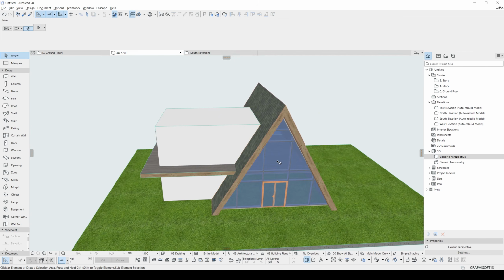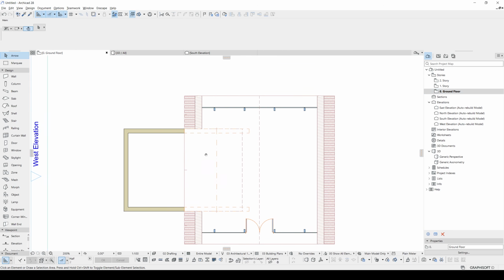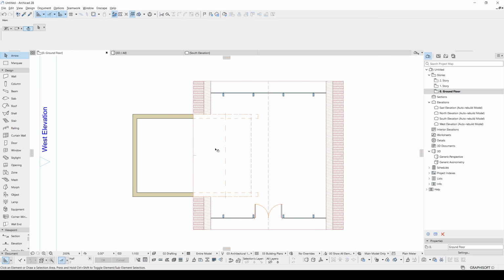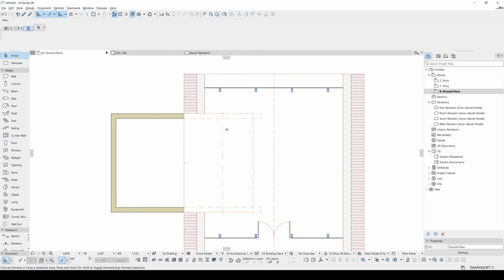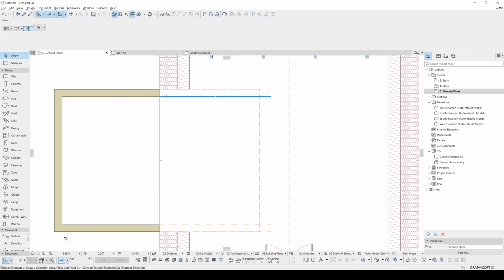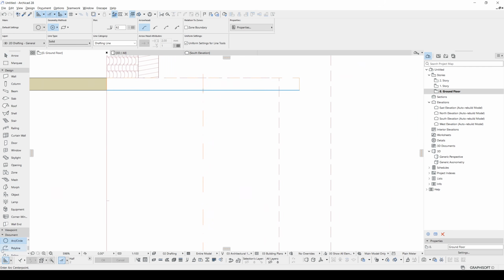Let's make our inner stair. I will go to ground floor. We can place it somewhere here or somewhere here. It's up to you. Let's make it circular. To do it, we are just going to make a circle, very basic circle. From the document, you can select this arc circle. And this will be the opening inside the circle stair. Maybe 50.